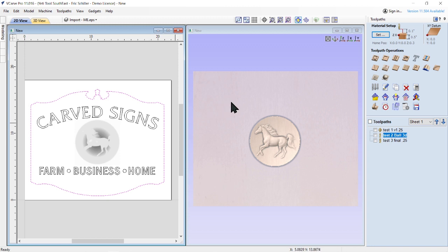So it's proper touch off of the tool that is required. So you can touch off using our touch plate. If you're not using the touch plate, or the touch plate is defective and you're waiting for a warranty piece or whatever, we go old school. Use a piece of paper and you lower your bit until you snag the paper.